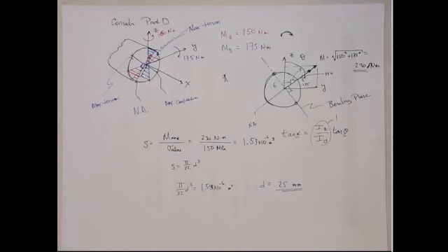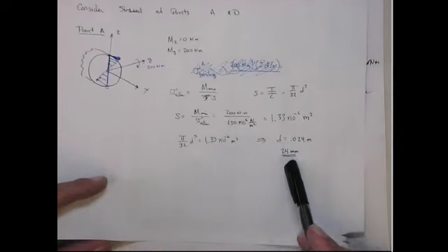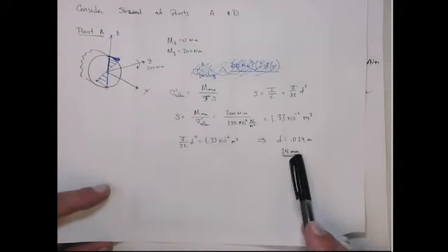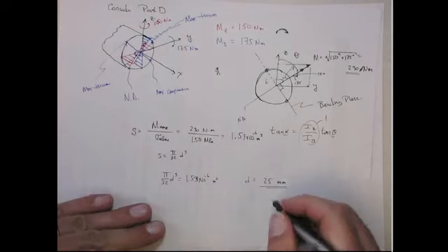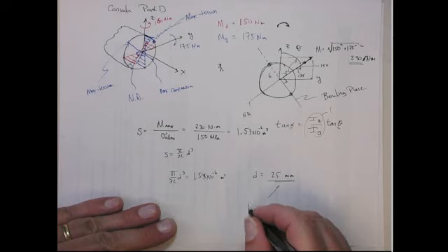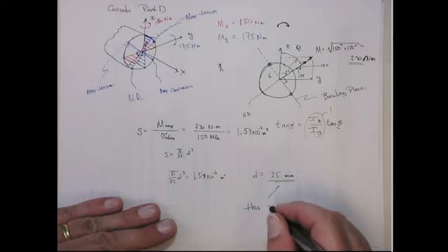From the prior analysis, they're pretty close actually. The shaft was supposed to be 24, you get a 24 millimeter shaft. So actually the correct answer is dictated by the case at point D. So this is actually going to be your answer. But more conservative, right?